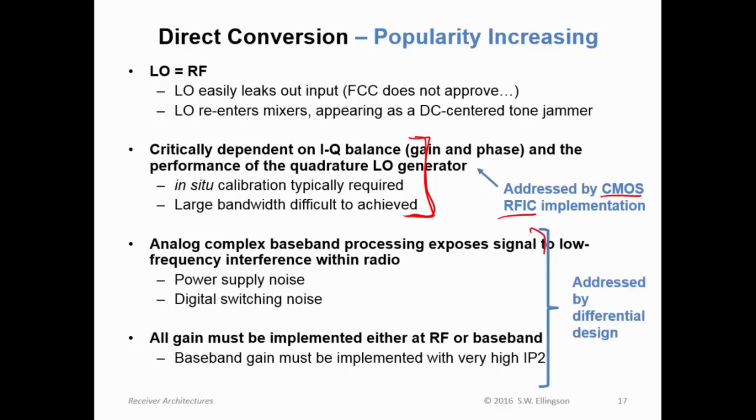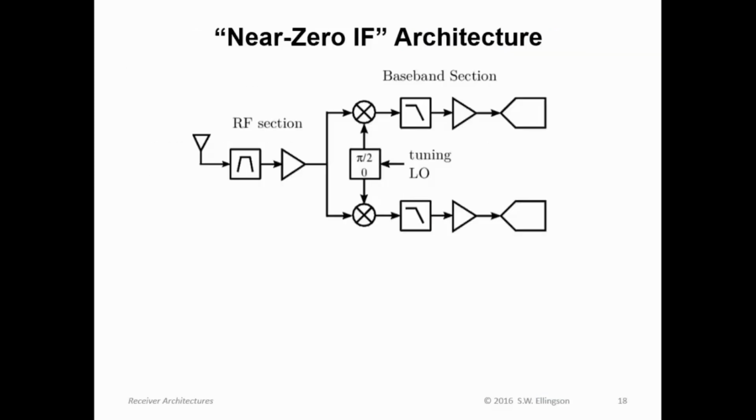Then these two problems are addressed by sound differential design. Because remember, differential design has intrinsically good common mode rejection performance, and good differential design has intrinsically good second order linearity. Now, a modification to the direct conversion approach is near zero IF architecture.